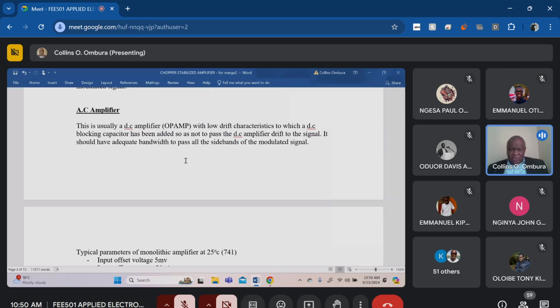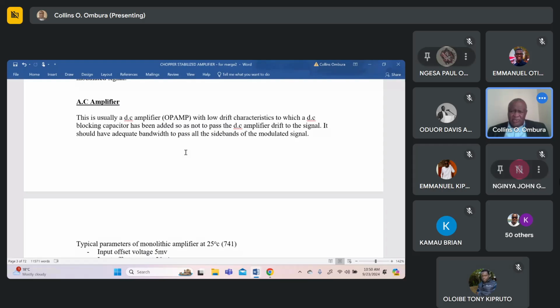Still, the noise margin between a logic 0 and logic 1 is almost a volt. So unless the electromagnetic wave induces about a volt in the input of your circuit, that's when it might interfere. So I hope that answers your question.